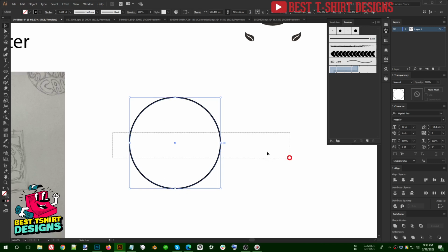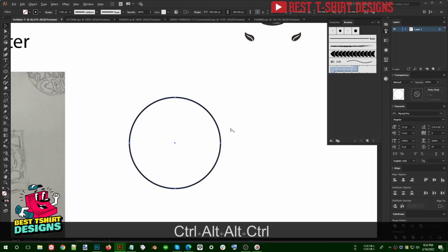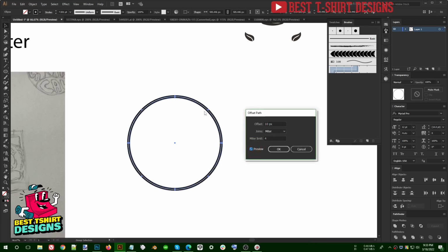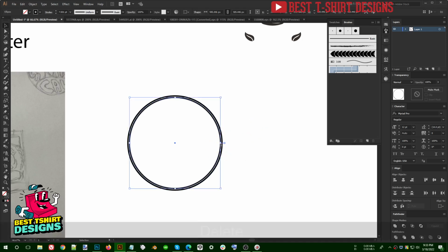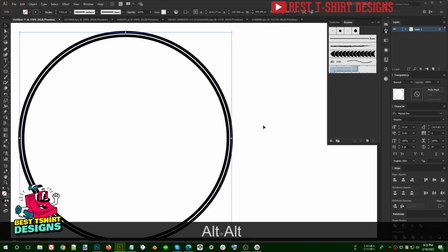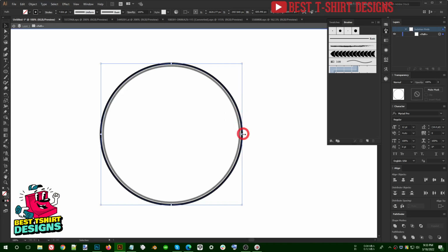You can see these two here and these two here, but I need more anchor points, and for that I am going to simply create an offset path for that ellipse, just any size offset path, it doesn't matter. Just click OK. There is another way of increasing the anchor points, but that's not important right now. So let's erase this center one, or maybe not erase, just keep it. Then I am going to select this outer one, and if I double click on it I will be able to isolate it.